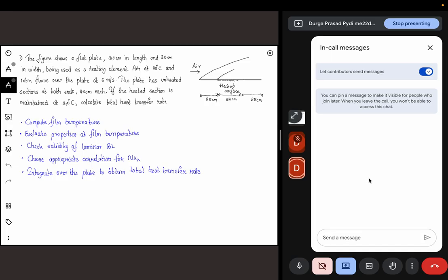If you are not in the laminar case, none of what we have discussed up until now is useful in any way. If turbulence is there, then the correlations are completely changed. So first you have to check whether your design is laminar. In order to check that, which number would you calculate to decide whether you're laminar or not? Yeah, Reynolds number is something that you have to calculate.